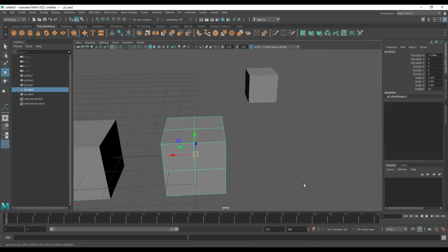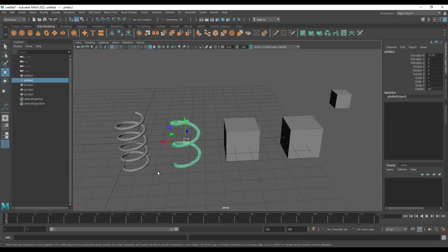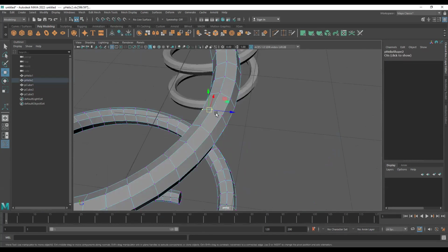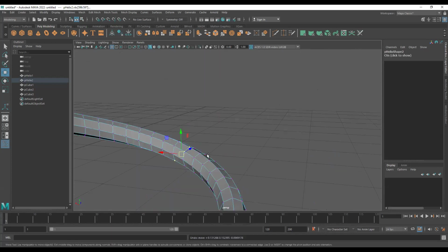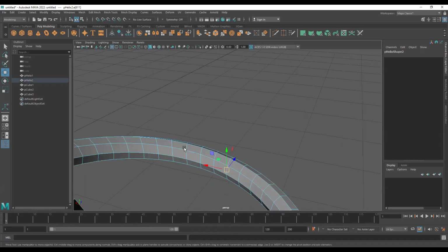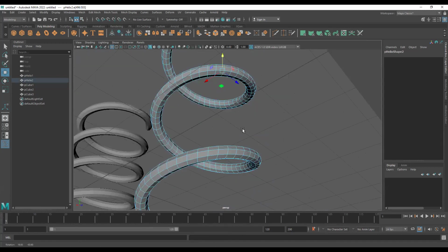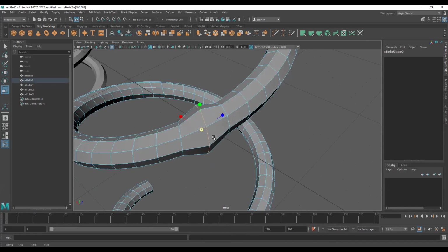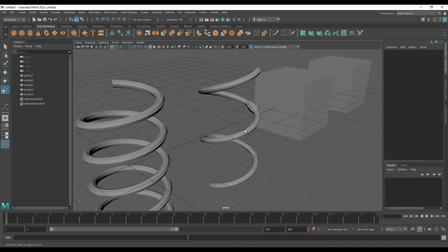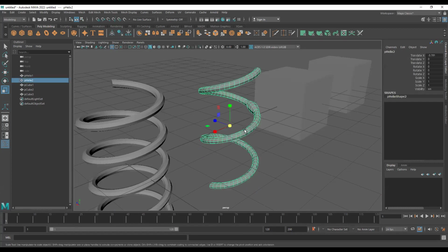Now we go to this box. This vertex, face, edges selection is common for everything. Go to vertex, select one or more vertices and move them. You can change the shape. Go to edge, click on one edge, or double click to select the round circle of the edge. What is the circle of edges known as? It's a loop. You can see we are selecting the loop and scaling the loop by using the R key. Over here, a little bit of bulginess we can create by editing the components of the polygon.